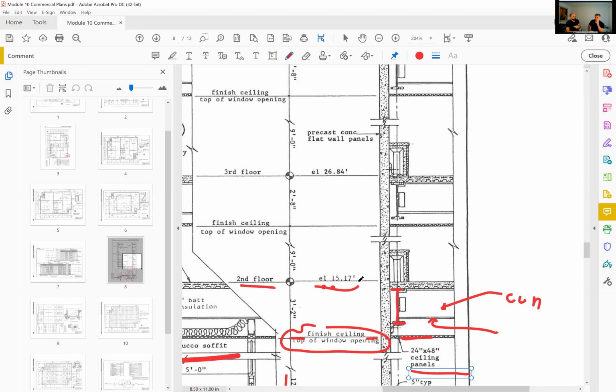Elsewhere in this drawing set, and maybe we can do a session on details, it actually shows you the dimensions of that floor slab, because this floor slab is a little bit different than the ground floor slab. The ground floor one's just a slab on grade. This one's composite steel deck. So we've got concrete on top of a steel deck, okay?